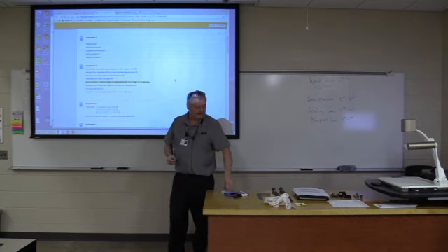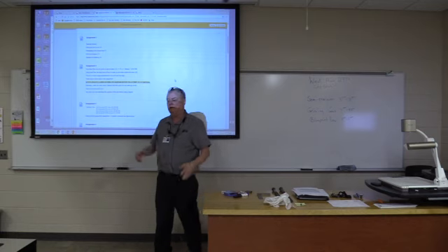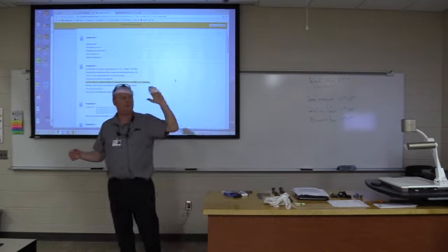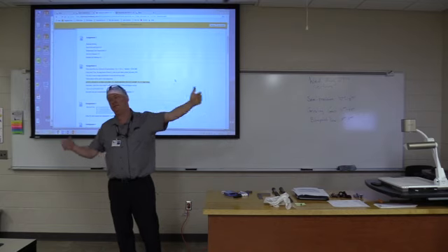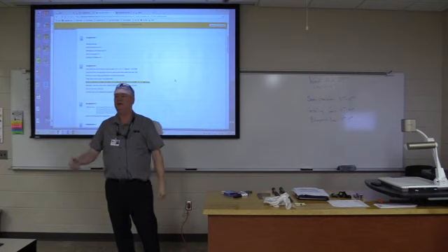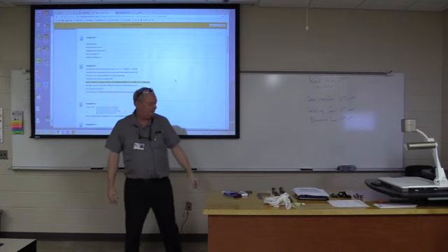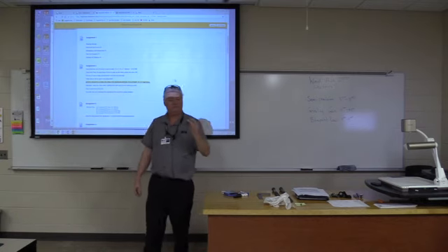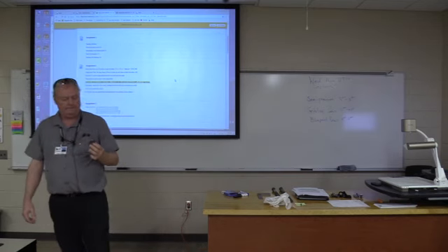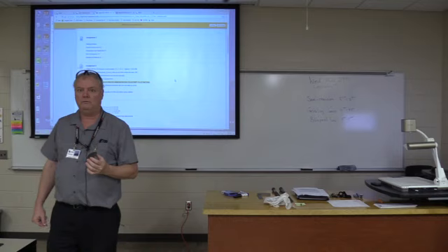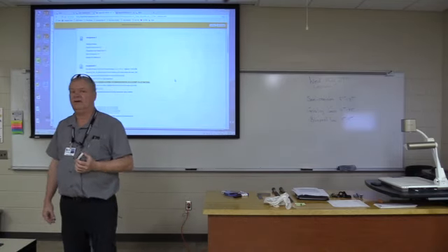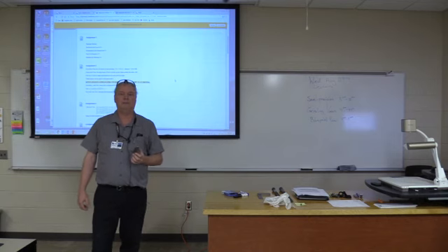As you looked around last week, I'm standing in the classroom right now. To the left of me is the shop, and if you go straight left past the 2 Mazaks, you'll see a material rack. And there you're going to have various kinds of aluminum and steel. 1018 is a kind of steel. It's a low carbon steel. It's easy to machine. But this and aluminum will be the 2 materials you'll be using in this class and others in the first semester.